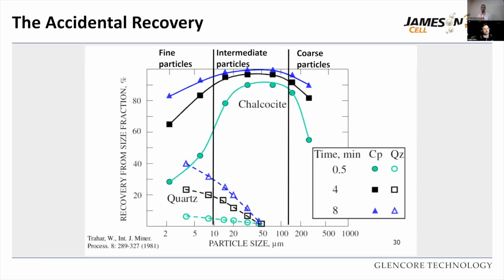But what's also interesting then is looking at the gangue material, which are the dotted lines now on the graph, which the recovery also increases for this as your time goes along. And it's particularly evident in that sub 10 micron range, which, as we've just spoken about, will of course be due to entrainment that you'll see coming to concentrate. So the more that you obviously try and pull those last bits and pieces of the target material, you'll also pull much higher gangue material into the system.